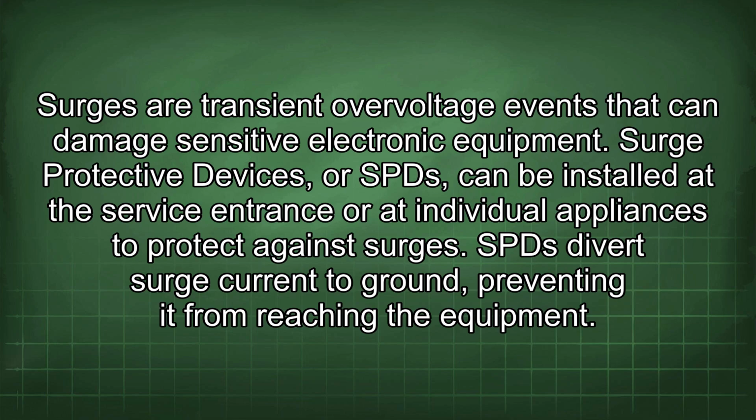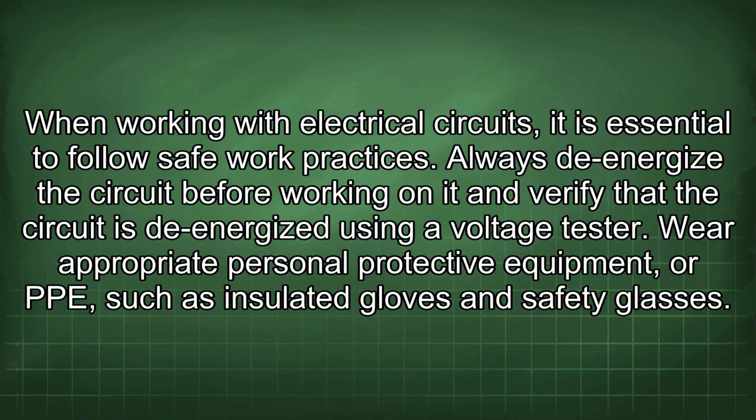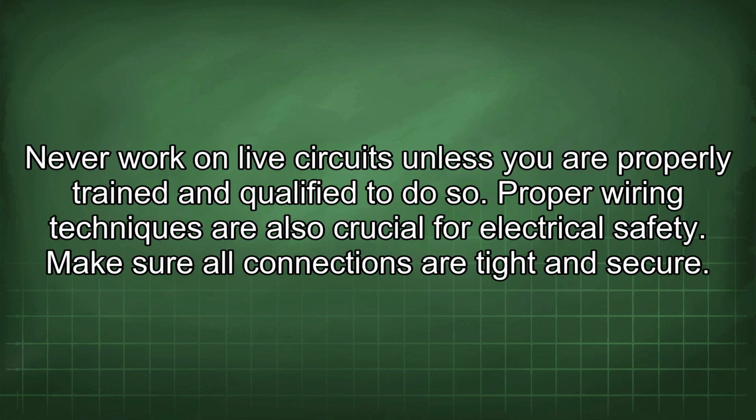SPD diverts surge current to ground, preventing it from reaching the equipment. When working with electrical circuits, it is essential to follow safe work practices. Always de-energize the circuit before working on it and verify that the circuit is de-energized using a voltage tester. Wear appropriate personal protective equipment, or PPE, such as insulated gloves and safety glasses. Never work on live circuits unless you are properly trained and qualified to do so.